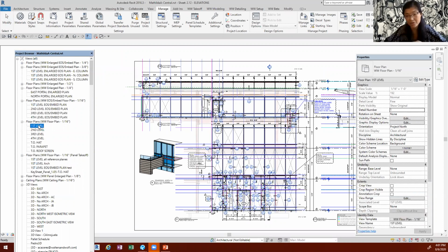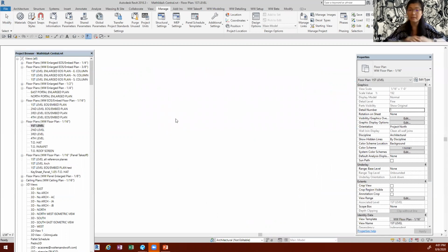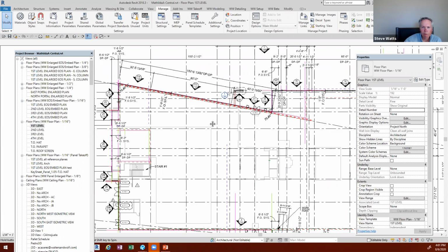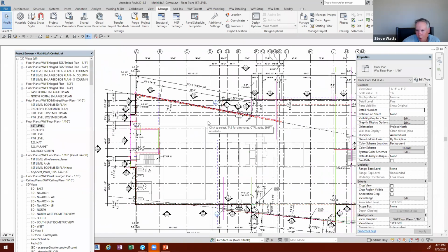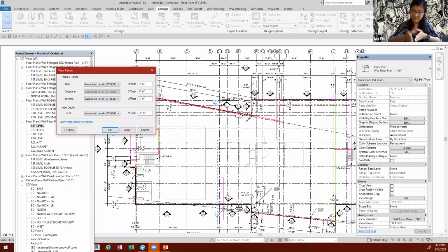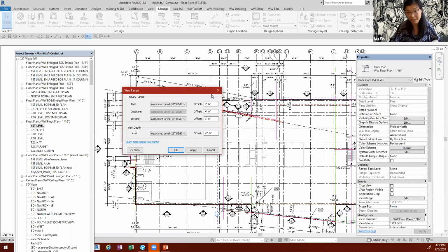I think James or maybe Celine can explain that one. Basically, the cut is where you see down. By architectural standards, it's 4 feet off the floor where you take the cut. But if you have a soffit above, where's the transition? A line projected to the bottom. You couldn't see it from just cutting that one.